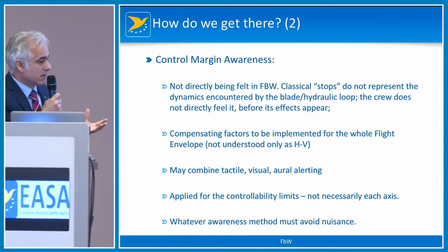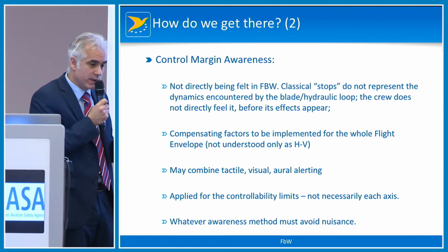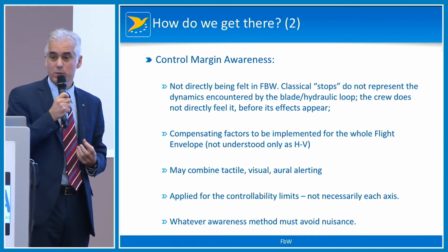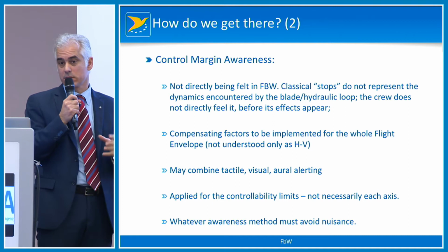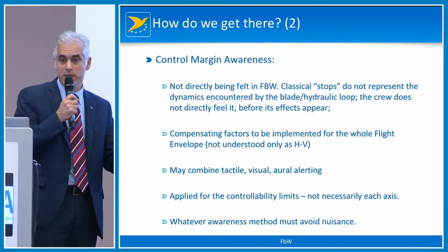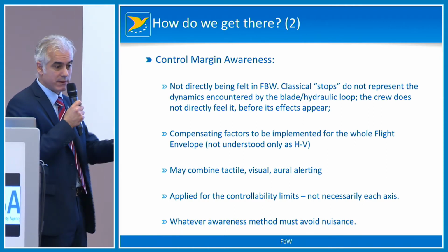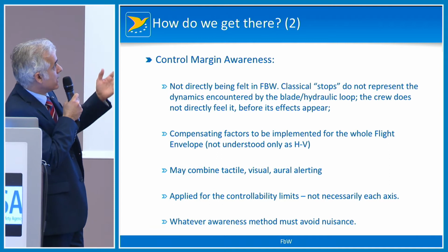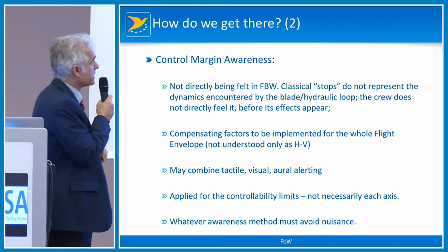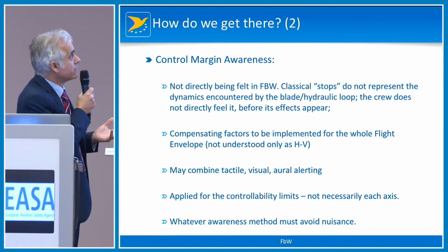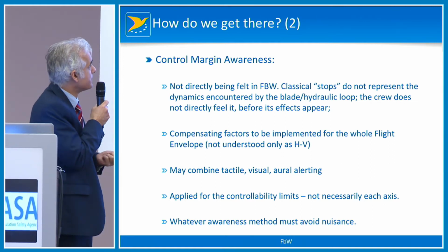Essentially, the root of that is because we do not fundamentally feel the limits, how we feel in mechanical helicopters or in limited authority systems, where a part of your actuator authority is being controlled by the flight control system and another part by mechanical links or via the trims. So we don't know where the "classical" limits are, please note the quotes.